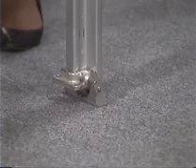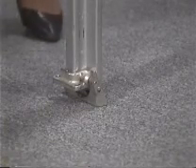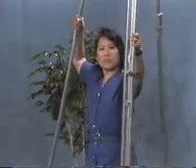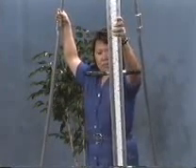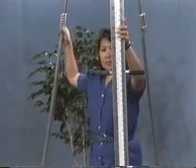Once placed on the boot, with the use of the bubble level attached to the back of the rod, the legs adjust and clamp to maintain the rod on a stable vertical plane. These rods are made in matched calibrated sets. Thank you, Carol, for your help in demonstrating that equipment. Chapter 2, Section 8 of the Caltrans Manual gives a good detailed discussion of the equipment used in differential leveling.